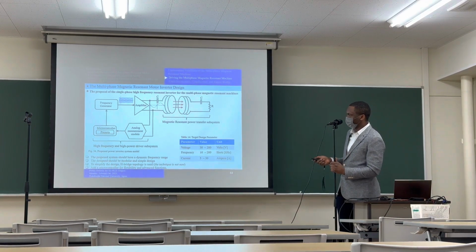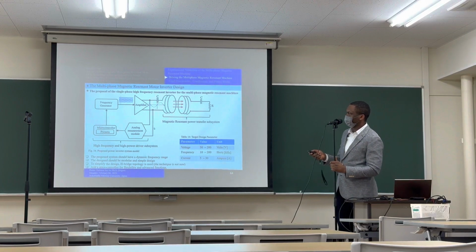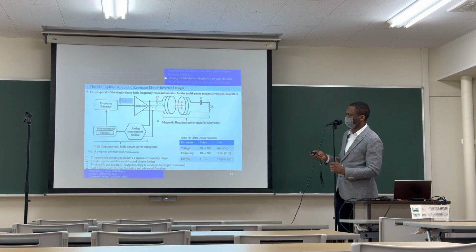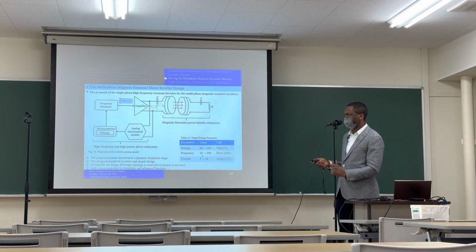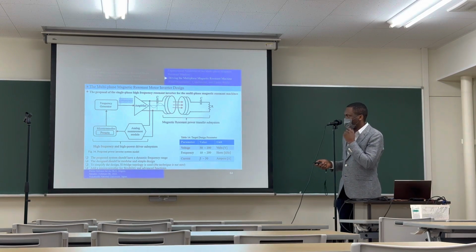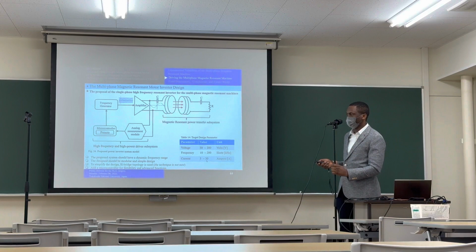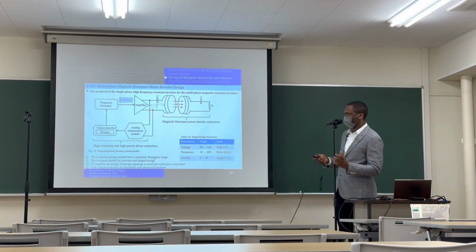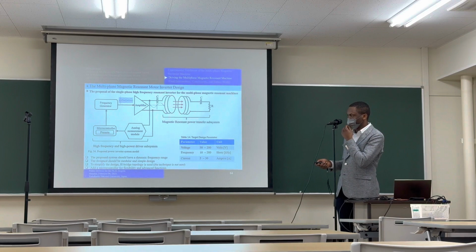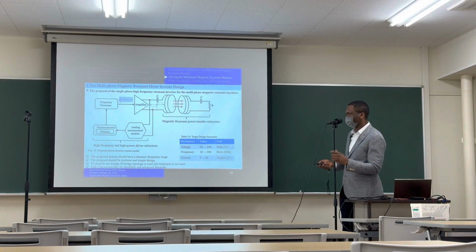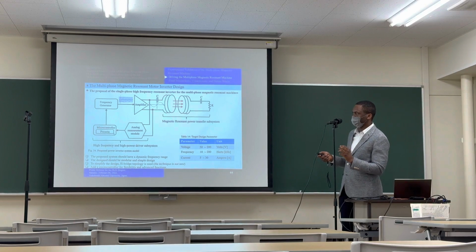But for this electronic system design, this is going to be the target design parameter. We want a system that will have from between 50 to about 200 volts, and the frequency to go from 10 to about 200 kilohertz, and we want the current to be from around 5 to 30 amperes. The main idea of the design is that we want something easy and modular, so that you can easily add it. We're going to use a very simplified design, using design techniques that are well known, nothing new. And we try to make some flexibility so we can change the frequency.